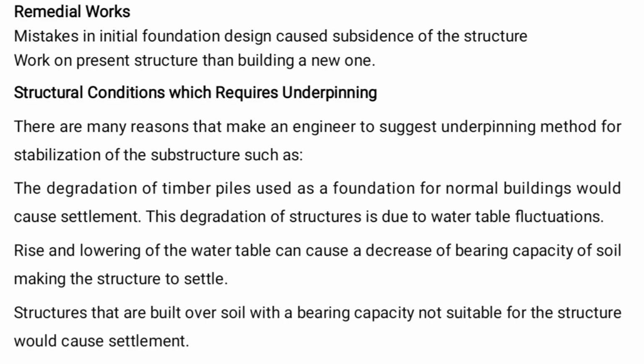The stabilization of substructures, such as the degradation of timber piles used as a foundation for normal buildings, would cause settlement. This degradation of structure is due to water table fluctuation. Rise and lowering of the water table can decrease the bearing capacity of soil, making the structure settle. Structures that are built over soil with a bearing capacity not suitable for the structure would also cause settlement.